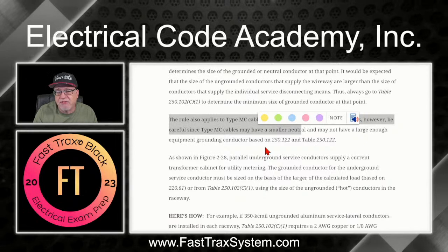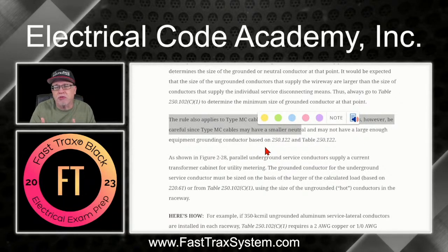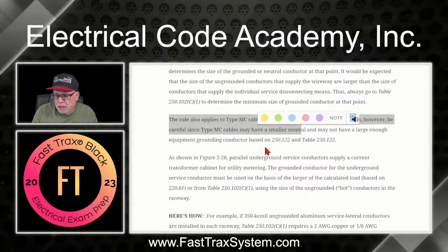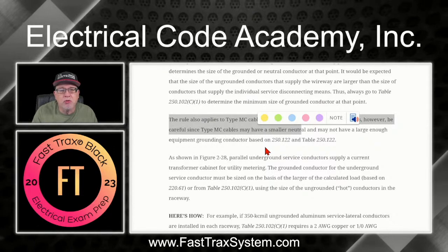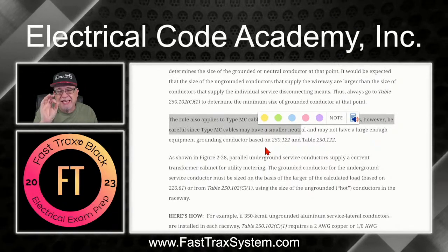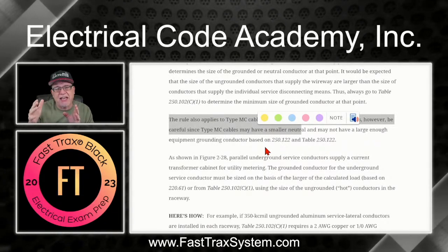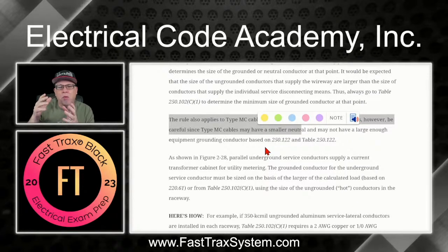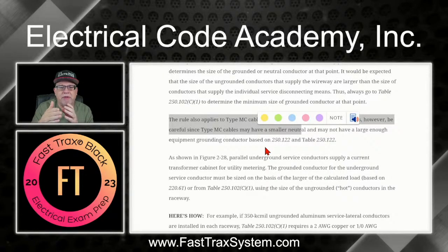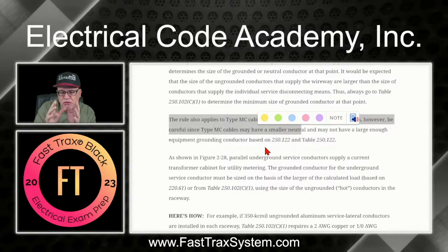So that means you're going to have a special MC cable made or special tray cable made to do this, or you're going to have to utilize some allowances in 250.122(F)(2), and that is where you'll run them in parallel in a cable tray, for example, or raceways, whereas you get to run one full-sized equipment ground and you get to use the other undersized equipment grounds in each cable together to allow you to use off-the-shelf MC or tray cable.